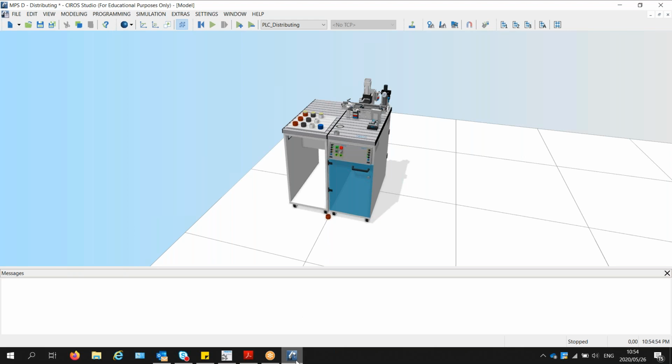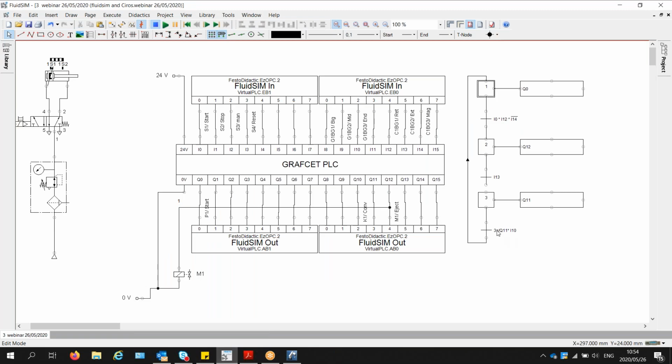So which is why you will see that I'm using this strange command here to say that I'm using the output, which is output 11, the conveyor, that the conveyor is running, it's high. So basically I'm delaying it. I'm using that as an input to the timer to say I will delay the off state of the conveyor for 3 seconds, so that after 3 seconds the conveyor should turn off.